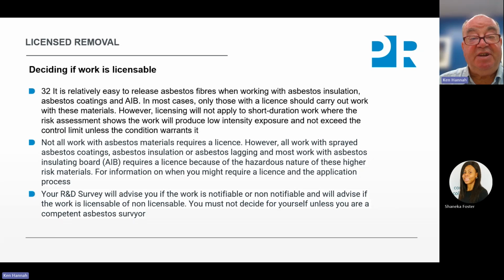So it's relatively easy to release asbestos fibres when working with asbestos insulation, coatings, and asbestos insulation boards. In most cases, only those with a licence should carry out, well, in all cases actually, should carry out work with these materials. However, licensing will not apply to short duration work where the risk assessment shows the work will produce low intensity exposure. So this may be a small amount of floor tiles where the adhesive contains asbestos.